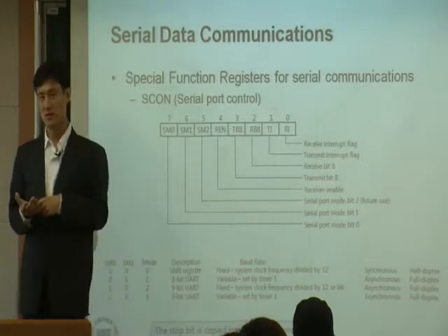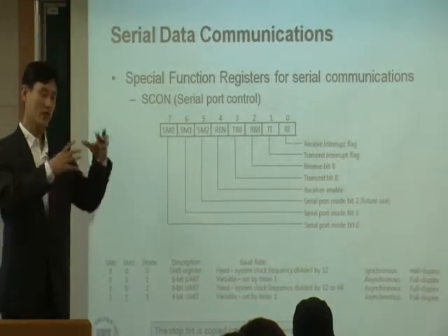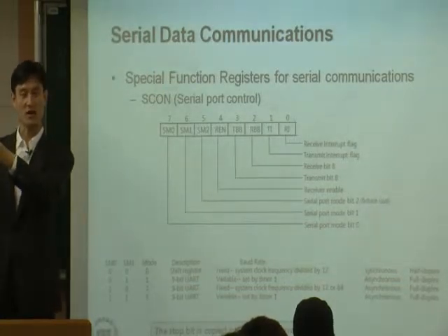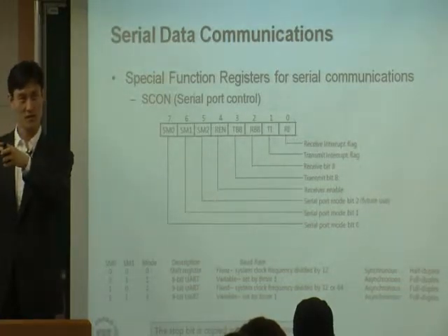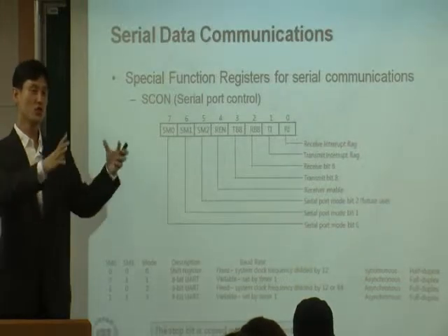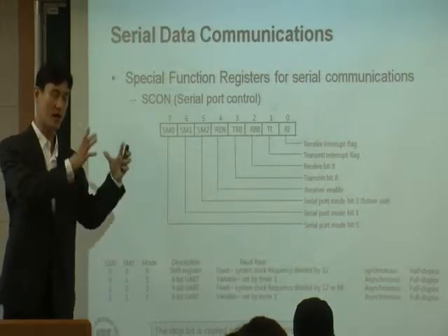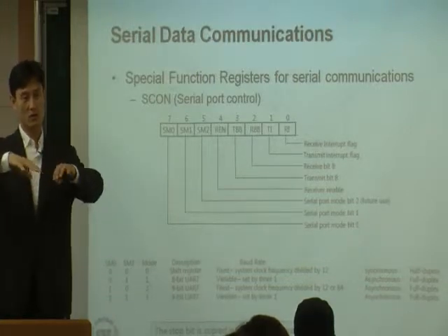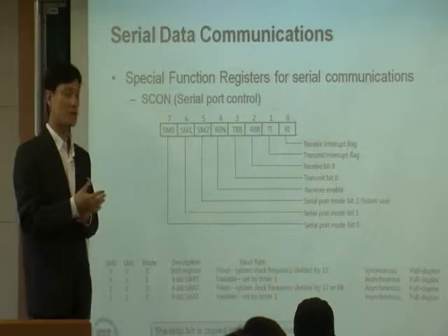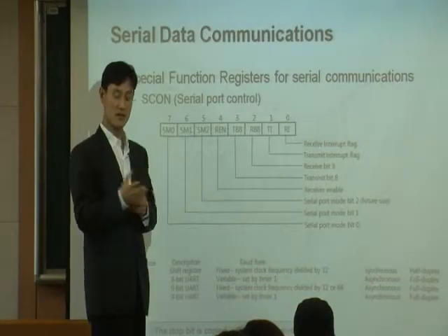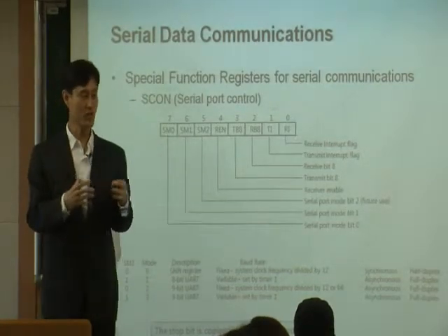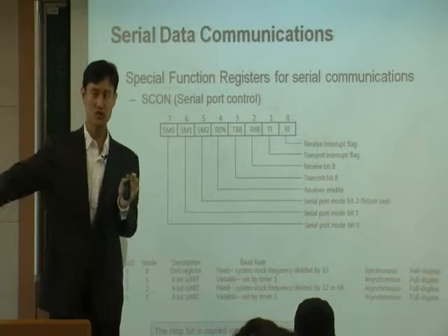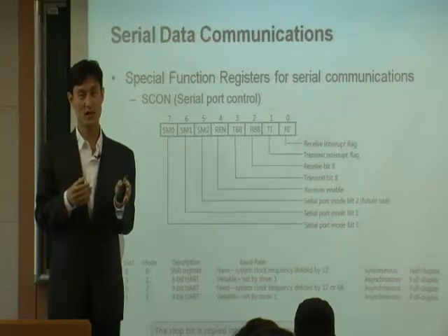Remember the timer interrupt, okay, mentioned earlier. We have a timer hardware block. We also have a separate interrupt hardware block. So sometimes if you want, you can use the timer hardware and also the interrupt hardware, all together. That's probably the best way. But if you want, you can still use only the hardware timer without interrupt. You can still do that.